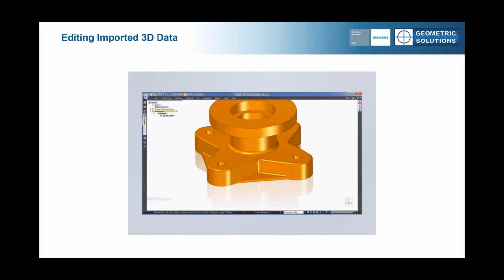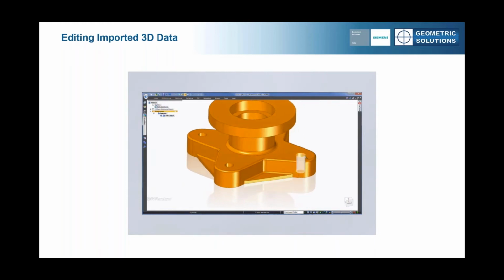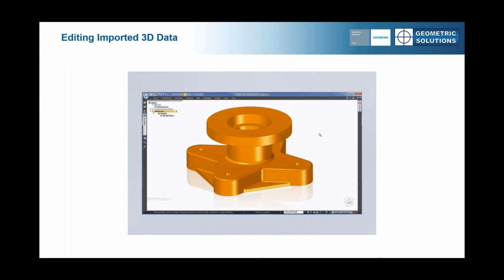But what if you prefer editing existing dimensions instead? Well sure, just click a face and Solid Edge will provide a dimension for you on the fly, ready for you to edit. Again, notice the intelligence here of all of the holes changing as if part of a pattern feature. And if you want to add your own dimensions, you can do this in 3D, no need for sketch work. We'll add a dimension for this thickness, then reduce that to 6 millimeters. Notice the control we have in keeping that top face fixed.